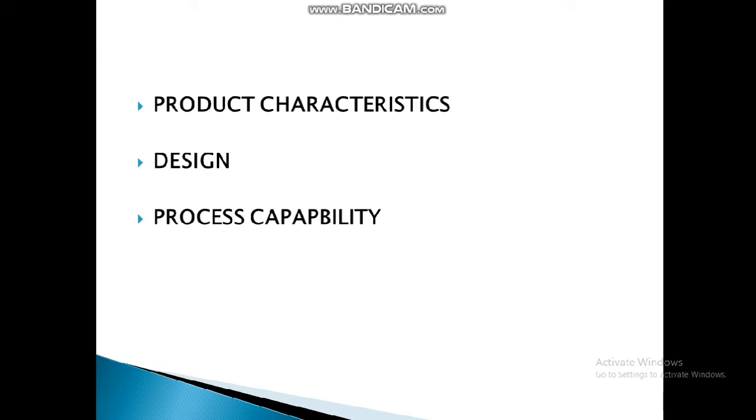Process capability. Process capability is the ability of a conversion process to produce a product that conforms to design specifications. Since the performance of machines and people used in the conversion process varies from day to day, the process capability is described by a range of variation from the design specification. That is, the variation expected under normal working conditions. A statement about process capability is thus a statement about product uniformity instead of various parameters of the process.